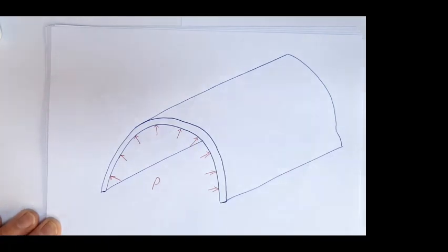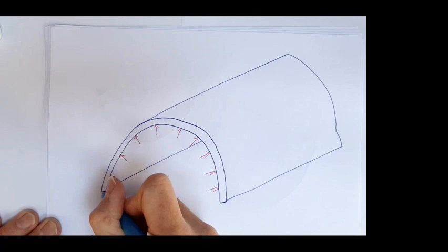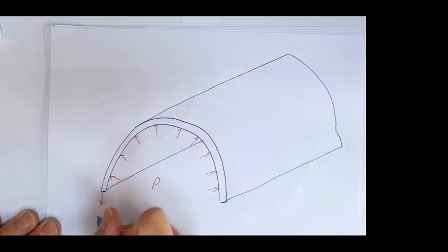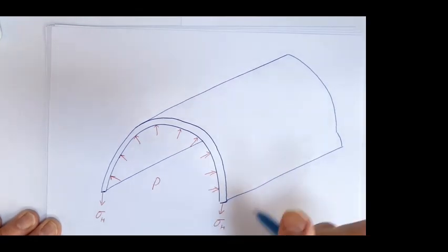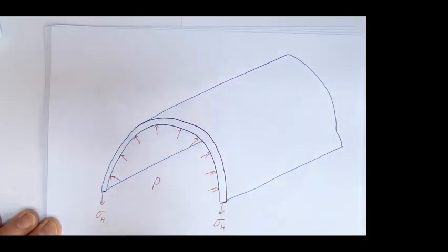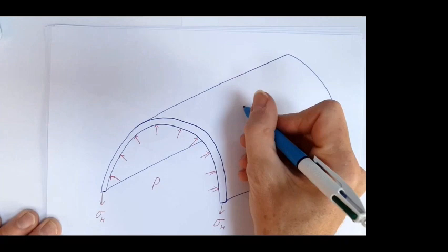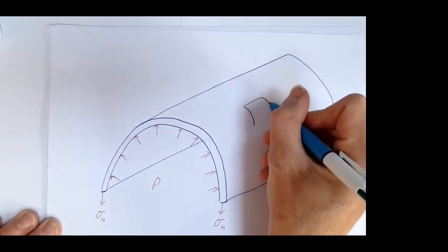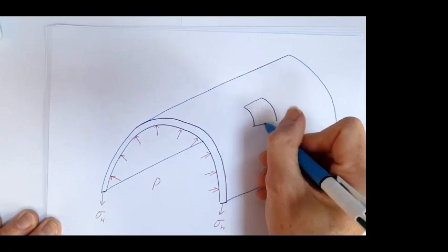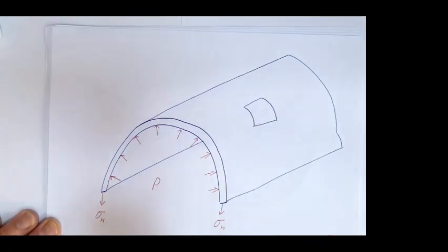That's going to set up some stresses. So on these bottom faces, you would have stress, and we're going to give that a subscript H for hoop stress. It's acting in the hoop direction. Because if we consider a small section of material sat on that surface, actually there are three mutually perpendicular stresses.